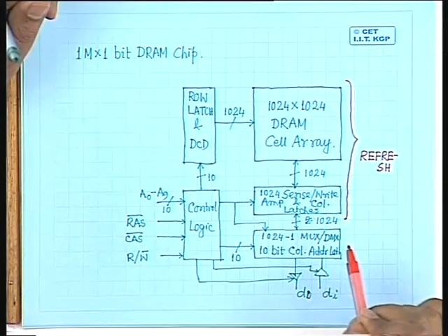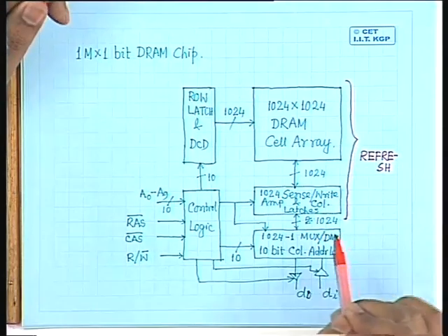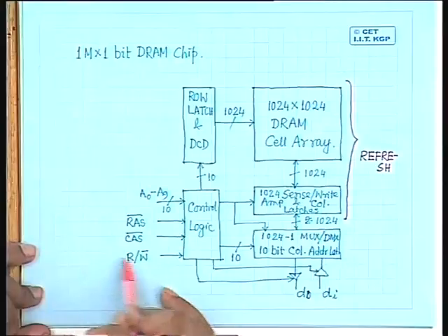Please repeat in which case? So as I said, in case of a DRAM cell, if I perform any read operation, the capacitors are going to be discharged. So I have to recharge them, which is done by the sense write amplifier portion. But even if I don't perform any read operation, the capacitor gets discharged if it is left untouched for a long period of time. So I have to perform some refreshing operation. And because there is no read or write operation to be performed on this, that means the CPU does not want any data from the DRAM, so CAS bar will not be active.